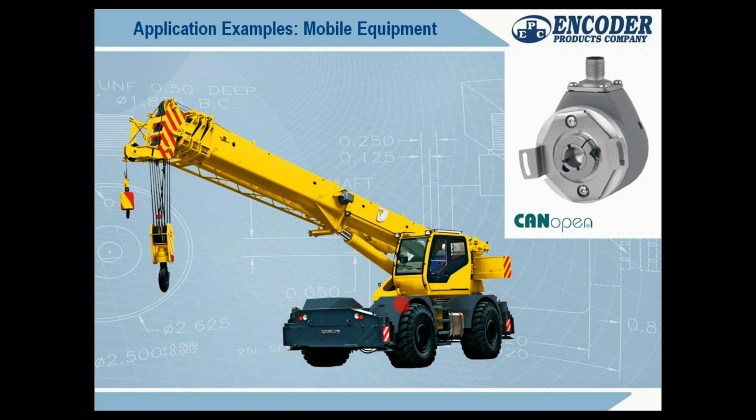Now that is on the drive gear. This ring gear is 180-something teeth, and this drive gear has teeth in the teens. So they use a multi-turn absolute encoder. They count the number of turns and the position, so they can take an encoder on the drive gear, but get a unique position for the whole rotation of the major ring gear.